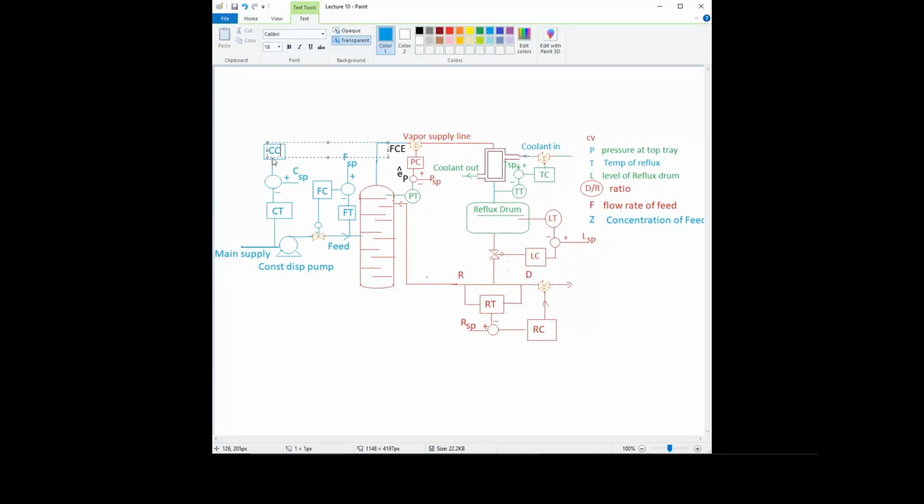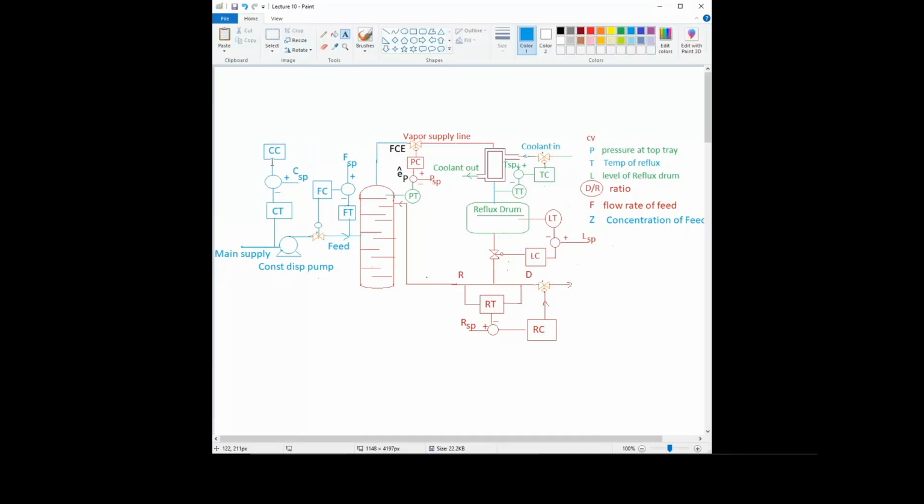the concentration controller, right? So here we cannot, like in the other cases, where we have to control the feed flow rate. We can measure the flow rate, then apply the control signal on the same feed, because by increasing or decreasing the opening of this valve, the feed flow rate can be increased, right?